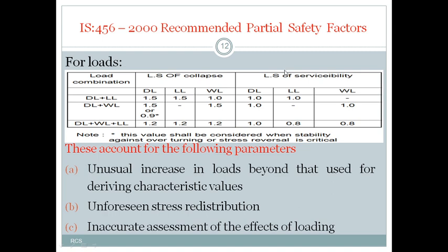And similarly, in the case of limit state of serviceability, if you are using a combination of dead load and live load, the partial safety factor for dead load is 1 and live load is 1. Similarly, if you are taking a combination of dead load and wind load, then for the dead load the partial safety factor is 1, and for the wind load it is 1. And if you are taking a combination of all these loads, dead load, wind load and live load, then the partial safety factor will be like this.